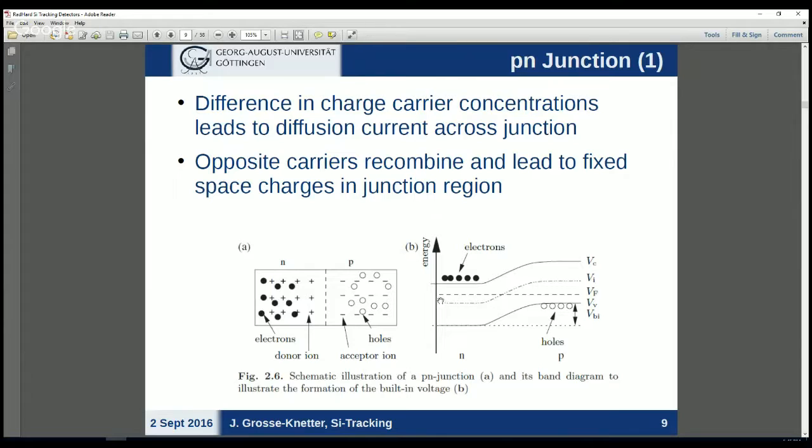And the Fermi level, which in one case is close to the conduction band for the n-type, will meet up with the Fermi level of the p-type, where it's closer to the valence band, and then the edge of the bands will move over in order to make the connection. So physically what happens is that the electrons in the n-type migrate further away from the junction, same for the holes in the p-type. In order to make this possible, they're simply shifted away from the junction because the conduction band is more difficult to reach for the electrons, same the other way around for the holes.